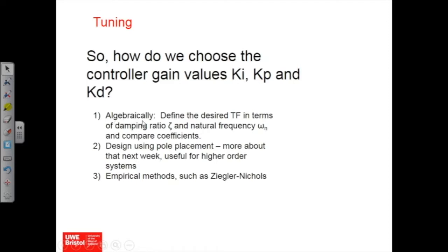Okay. If we've got a good system model, a precise system model, then the algebraic model is great. It's dead easy. Because we can do algebra, we can do it sitting at the desk, say, okay, set the controller to these values. But we sometimes simply don't know the coefficients. And the same problem actually exists with pole placement, because that's also dependent on the transfer function.